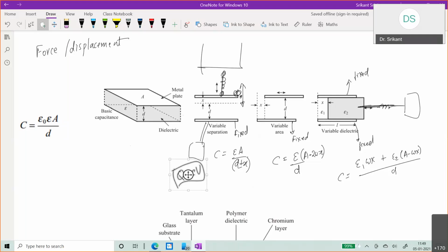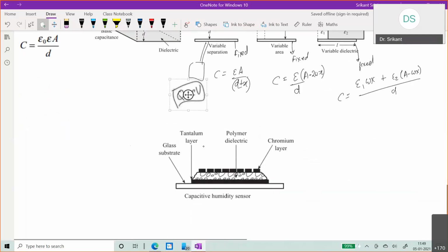So these might require more sophisticated measurement circuits. In fact, instead of a multimeter, you may have to put some BJT kind of thing, do some transient response, or use a peak detector circuit so that it captures the peak of the change. You have to be a little innovative about it.